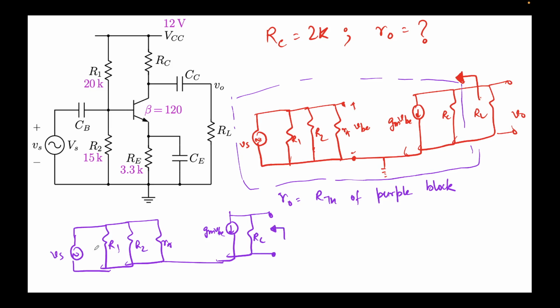And we know when you find Thevenin equivalent, you short circuit all the independent voltage sources. So this is an independent voltage source, right? This is the independent AC input voltage that we are providing. This means that to find RTH, Vs must be made equal to 0.